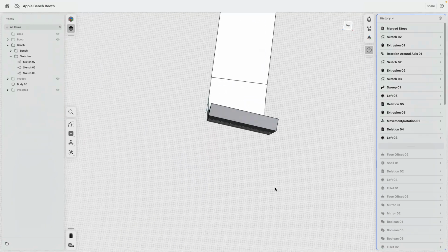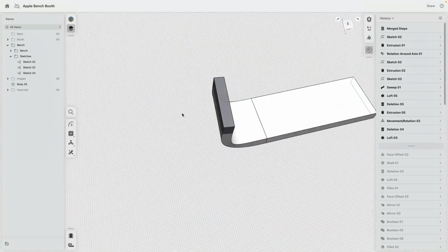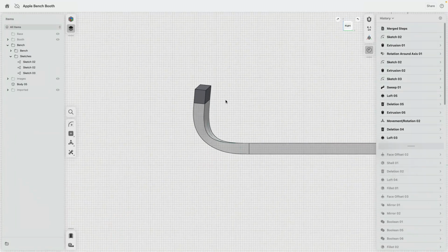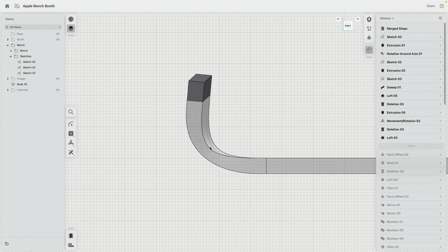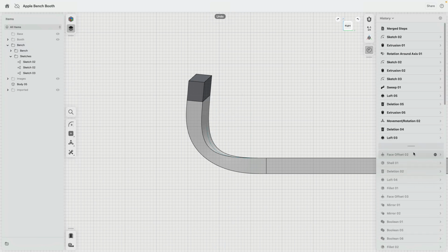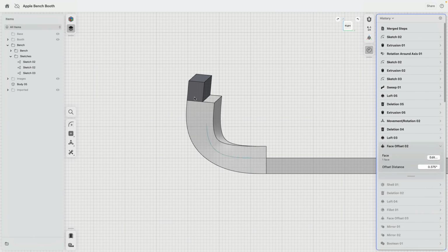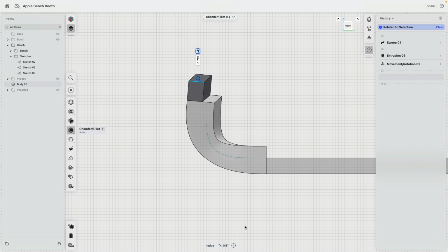Pretty cool, no? So you see from the top now how this lofted body has this edge. The problem of a solid loft, however, is that in this case, we can have the issue that the start and end points are okay, but somewhere in the middle, it gets squeezed. How do we fix this? Easy way, you select the interface, for example, and then we expand the surface. This is what I did here. I think I used 0.375 inches, and this is 0.5.